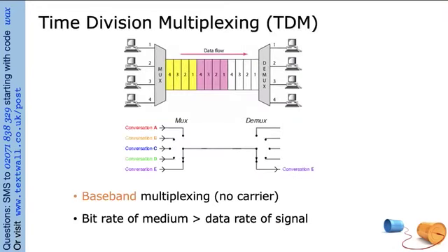Now, time division multiplexing is different. Time division multiplexing is generally for digital communications, and it's where we allocate time slots. And it's really important. So what you have is a clock, and that clock samples each of your signals. So assuming that your signals are analog, you would need a clock to sample them. If your signals are digital, then you don't need that.